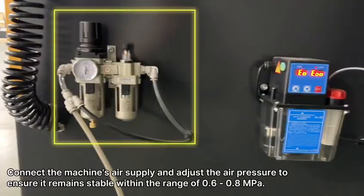Connect the machine's air supply and adjust the air pressure to ensure it remains stable within the range of 0.6 to 0.8 megapascals.